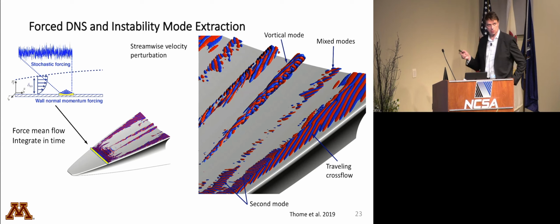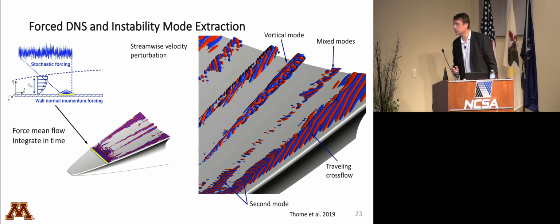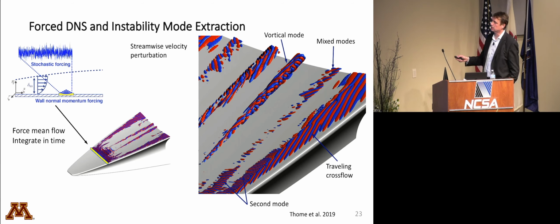And the flow field selects particular modes. It responds in particular ways. You get these 4 types of instabilities that occur on the bolt geometry. So this is clearly a vortical mode that is in that lifted vortical part of the flow field. These are very clearly traveling cross-flow modes, and if you play the movie, these worms, the blue and red worms, just happily march downstream.